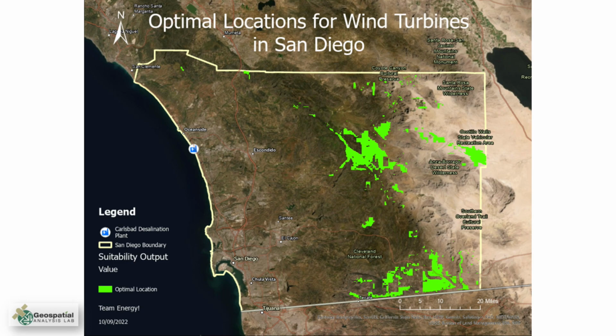To power the Carlsbad desalination plant, in addition to the proposed solar projects, which equates to 161 million watts of energy, only 21 wind turbines are needed, which equates to 589 million watts of energy. One wind turbine requires 1 square kilometer of land. Therefore, 21 square kilometers of land are needed for these turbines.